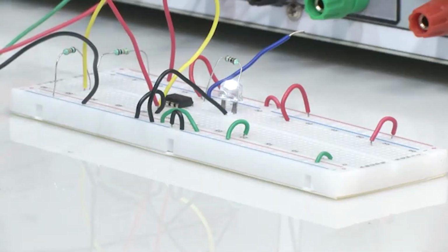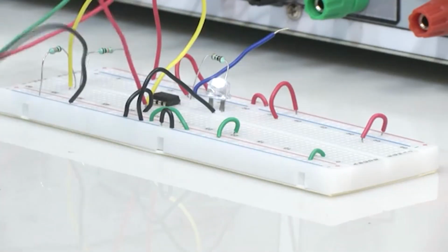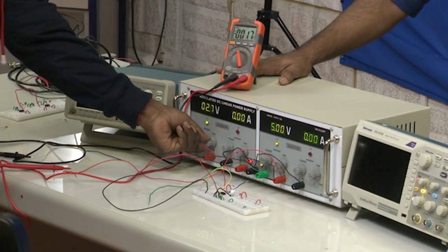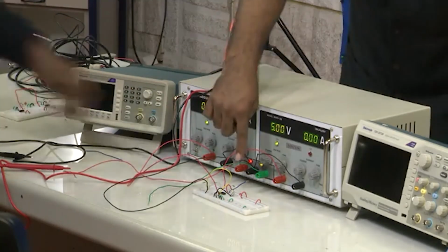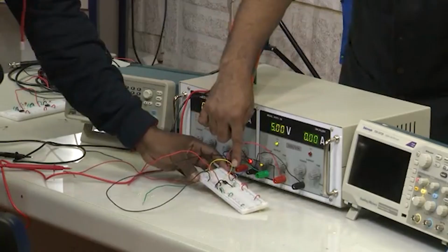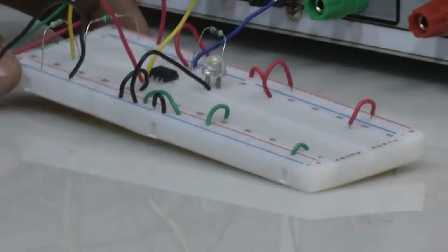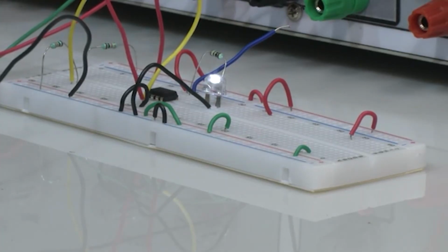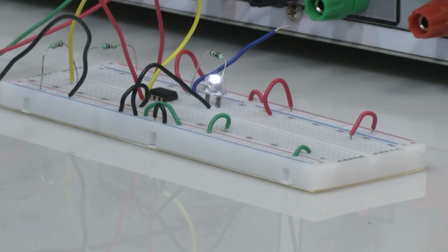Now, you can see here again, can you reduce the voltage please, so that students can understand. Reduce the voltage, you can see the DC power supply, he is reducing it to 2.4, bring it 2.4, yes. Now, you focus on this one which is your LED, and you cannot see the LED glowing, right. Now, make it 2.5. So, at 2.5, now you see it is slightly greater than 2.5. As soon as it increases a little bit greater than 2.5, you will immediately start seeing the LED glowing, that means that the output is high, very easy to understand, right.